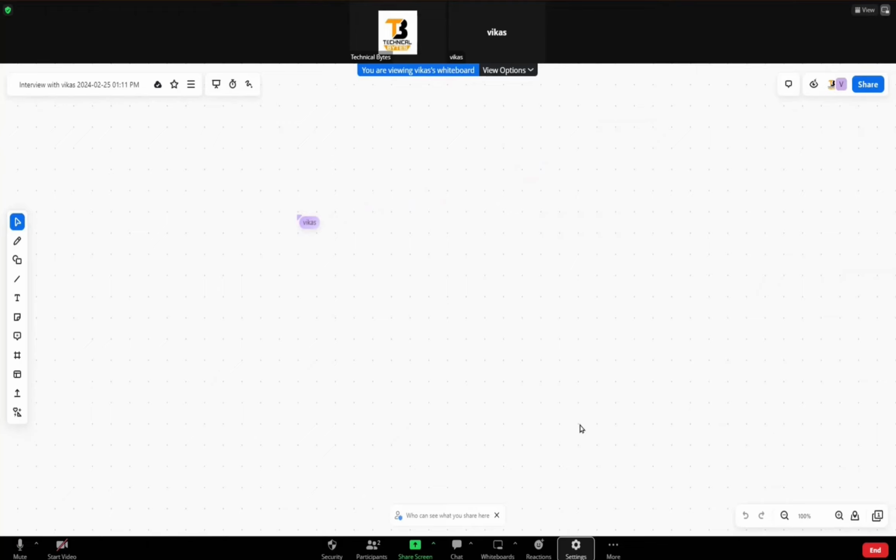I think it is prone to glitches or something, sir, because we are using the data path in the clock path, so it can have timing violations. Where do you think is the glitch? In the second and in the subsequent flip flops. Why is there a glitch in the second or third flip flops?